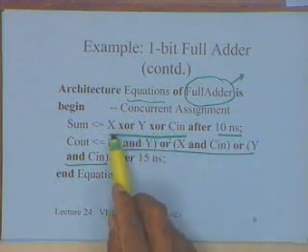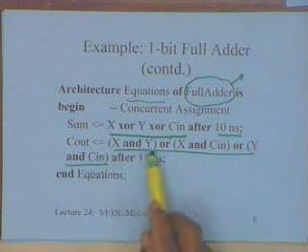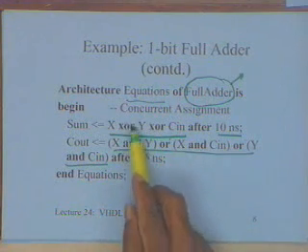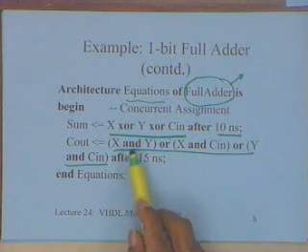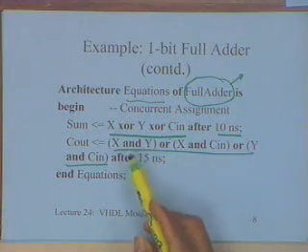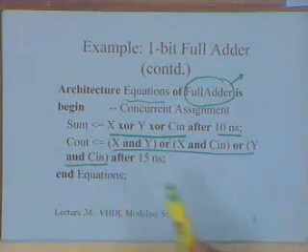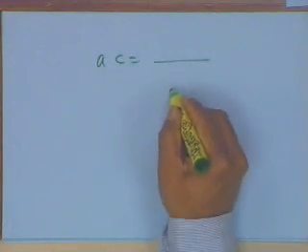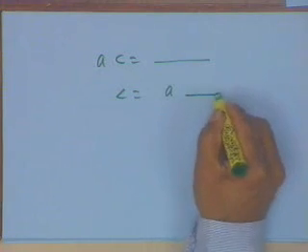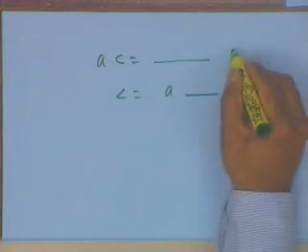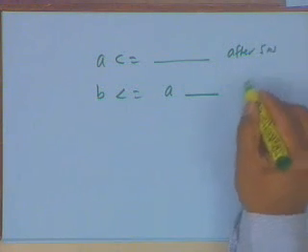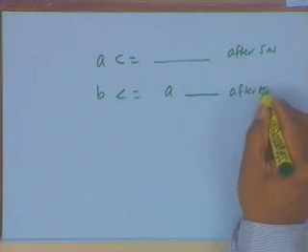It is not that I am going to proceed and assign to C out after 15 nanoseconds. It's not like that. Both of them are evaluated simultaneously. Order is not important. That's just the simulator which does it. This type of situation becomes important when you are assigning some expression to A and assigning some expression to A. Let's say this one contains after 5 nanoseconds and you say after 10 nanoseconds.